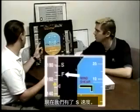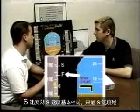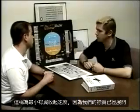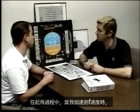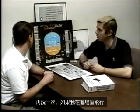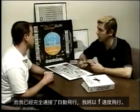Now we have an F speed. So describe F speed for me. F speed is basically the same thing as S speed, except F speed is related to flaps 2 or flaps 3. It's called minimum flap retract speed because we have flaps out when we're in position 2 or 3. And during takeoff, as I accelerate through F speed, I can then raise the flaps from either 2 or 3 up to 1. And again, if I'm flying around in the approach phase and I have auto flight completely hooked up, I'll be flying at F speed.